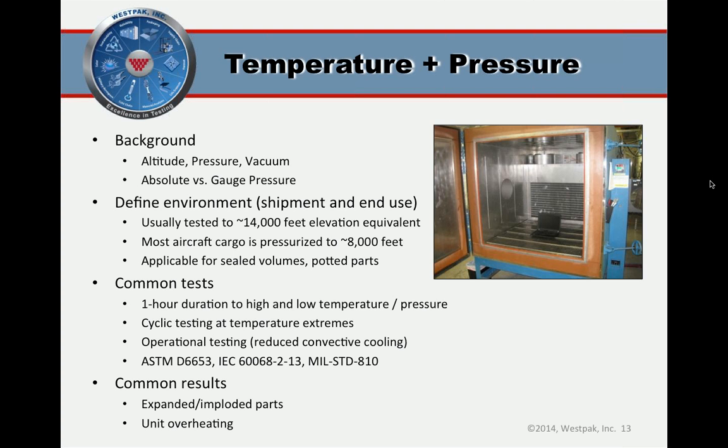So imagine our laptop. It's in the chamber at high temperature and at low pressure. So you're in the summer in the Rockies, and the laptop uses an internal fan to force air through and cool itself. Well, there's a lot less air for it to cool itself, and that can create operational issues. So that's one of the things we're looking for in this testing. There are many standards describing altitude, not so much the combined temperature and altitude. Again, that's going to be very specific to your product requirements.